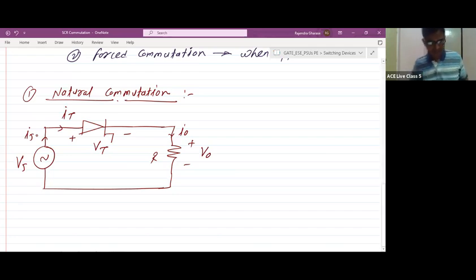So now here, if I indicate this type of symbol in the circuit, it is like an anode, cathode, and gate, okay. It looks like the gate circuit, or the gate-cathode circuit, is open, but assume that the gate-cathode circuit is connected there, okay. Some elements are connected there. We need to assume that between gate and cathode we have a circuit here. It is not shown here, but the circuit is present, okay. Otherwise we cannot turn on the SCR, right?